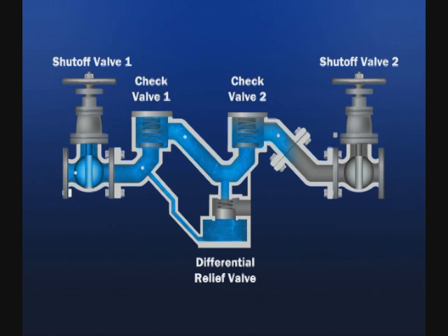Water flows into the first check valve. As the first check opens, it fills the reduced pressure zone and the top of the diaphragm at the relief valve at a minimum of 2 psig, 13.8 kPa gauge. If there is a back pressure, backflow, or back siphonage, both checks will close and the relief valve will open, venting water to the atmosphere.